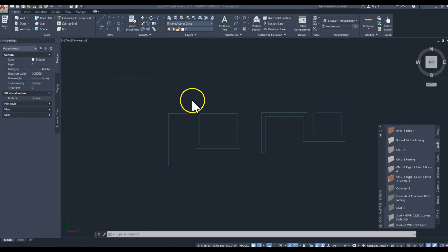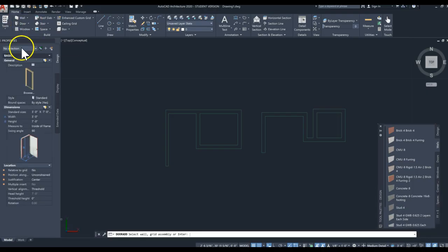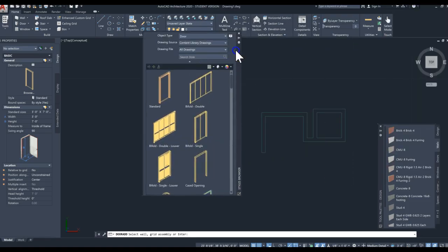All right, the next thing we'll see how to add is a window and a door. So click on the home tab once more. Then let's do a door first. Click on door. And you see now various features for our doors. So if you were to double click here, you can browse various types of doors. And maybe you choose, oops, it popped up in a different monitor.